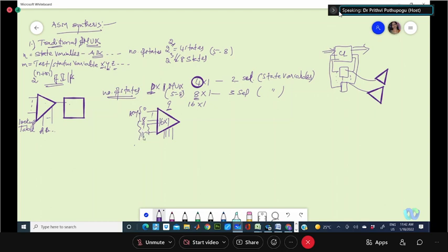Any modification to your ASM, if you want to add states, there is flexibility. Only try to derive these added state equations. Because we were dealing with this as, say, if this is related to a flip-flop, a variable. We were saying A0, A1 and so on to A7. Likewise, you derive A8 to A15. So that is the flexibility you are having.